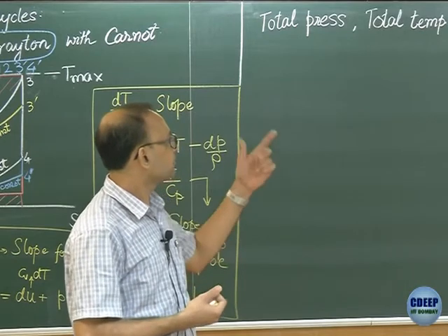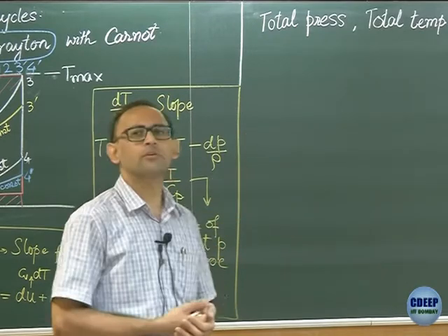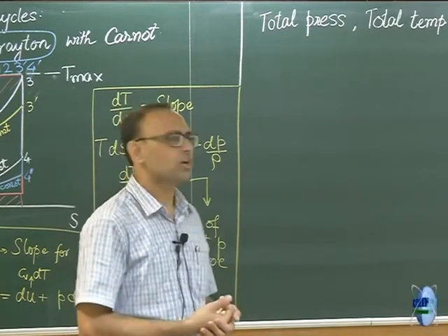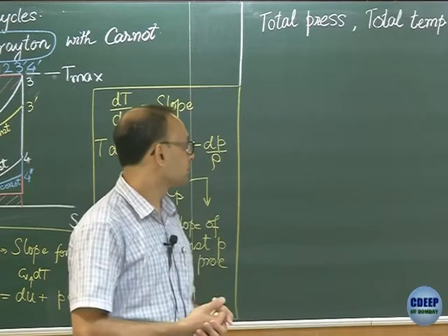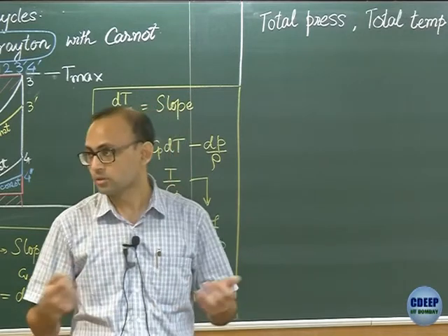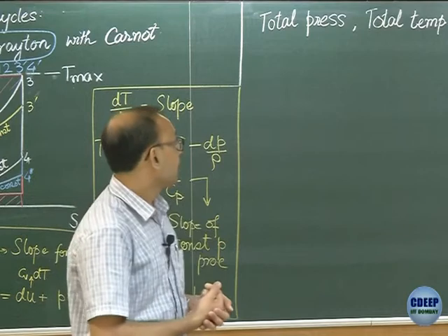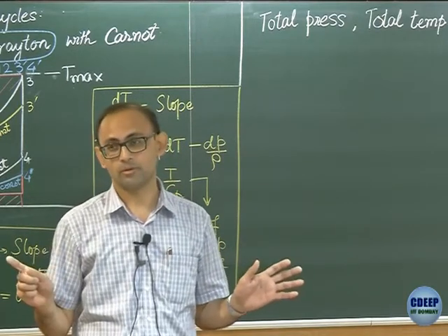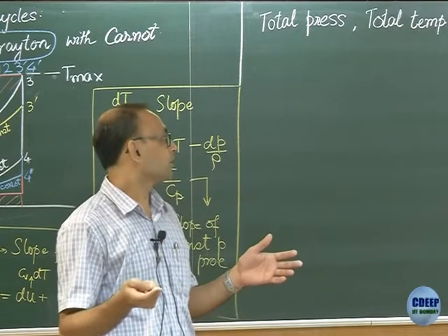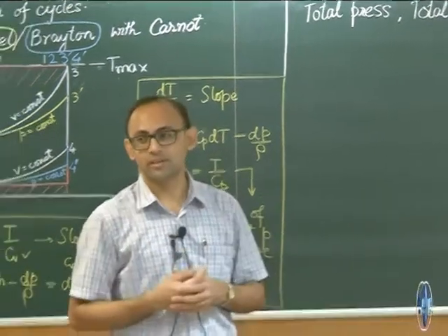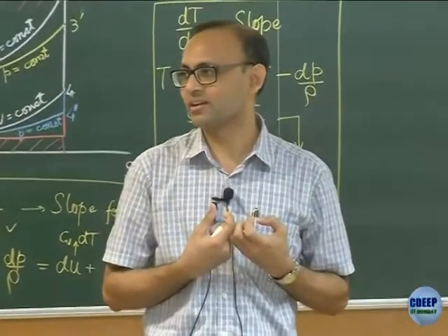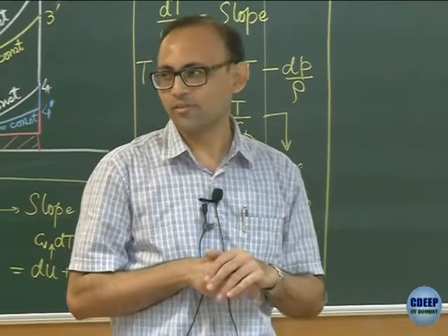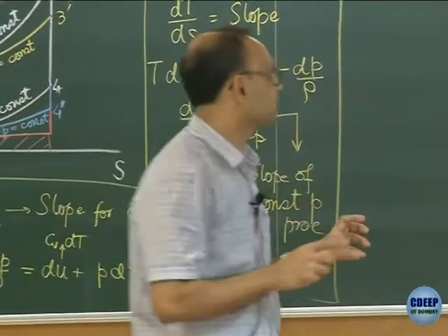The change in total enthalpy is because of heat transfer and because of external work. External work is most of the time shaft work. As we saw in the midsem paper, even if there is friction, it does not come into the picture. And external work is anything which is not flow work. That's another way of thinking about it. Anything which is not flow work has been dumped into external work, and the flow work has been taken out of work interaction and dumped into enthalpy, right? So we have an easy way of putting things together.